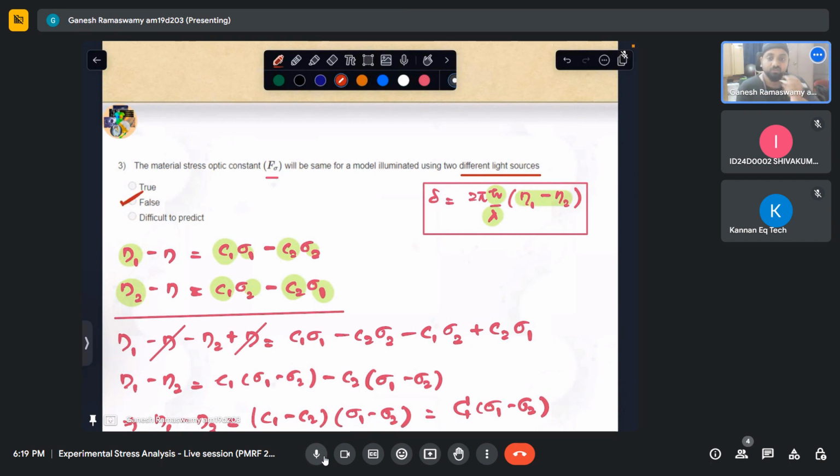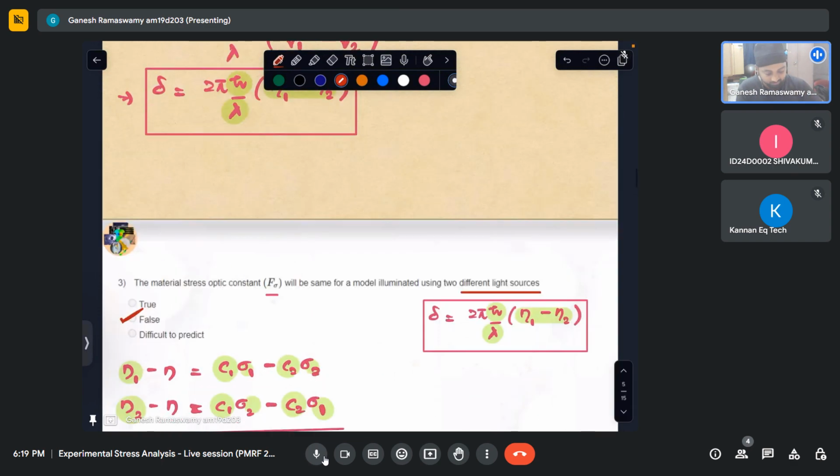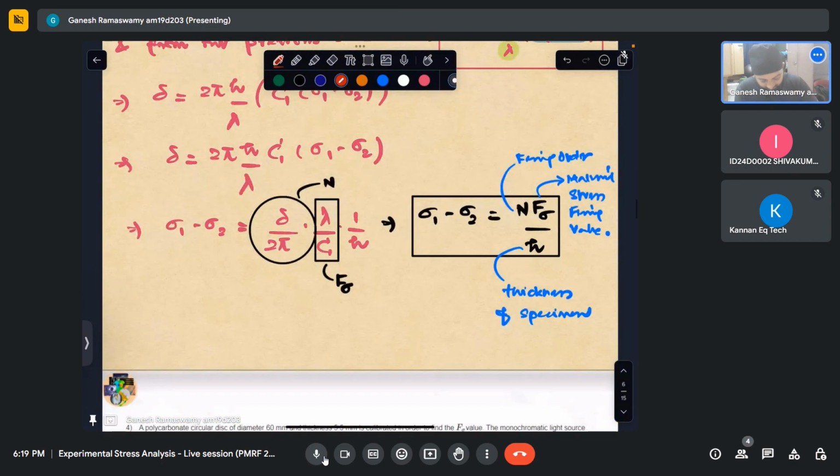Where is this important? Now we saw that we generally develop a calibration. For example, we saw in one of the sessions that we had a light color table where there was one black color in the middle for a beam. Then there was some pinkish color for the fringe order one. Then blue, green, things like that. So this is specific to one light source.